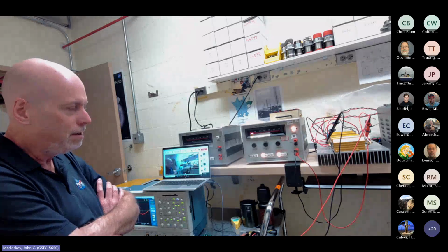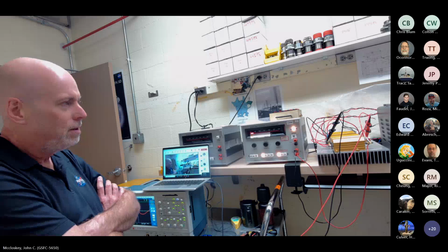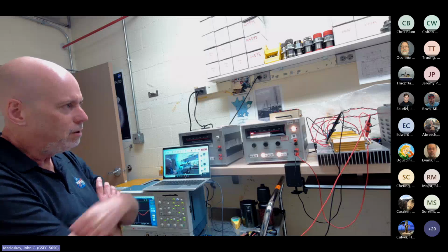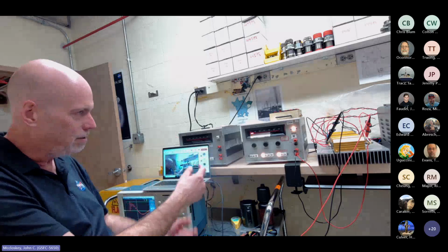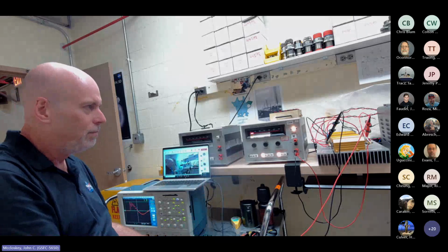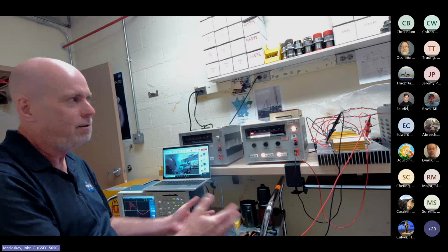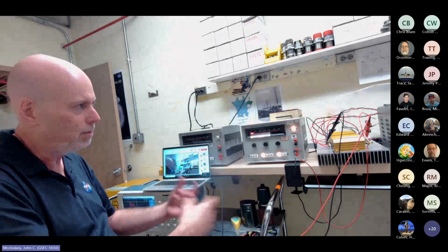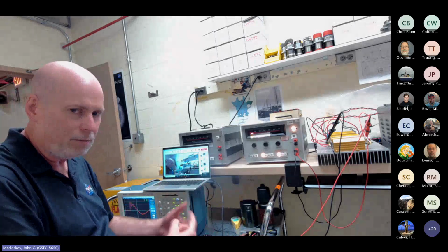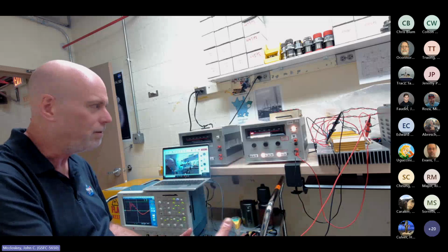If you find it early enough, maybe you can improve your filtering or what have you. But generally speaking, if it's late in the flow and you see that sort of thing may cause a disruption, may cause your box to reset or whatever, then you can handle that in mission ops. You generally shouldn't be doing any real critical things while you're cycling power to boxes intentionally, right?